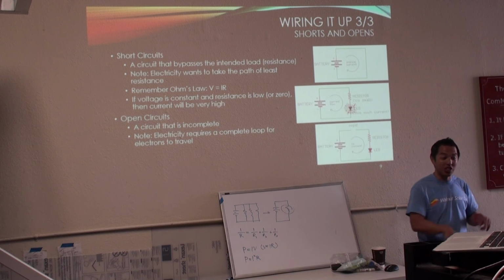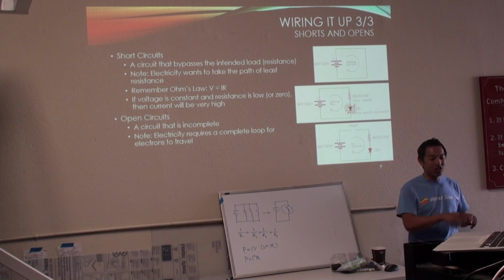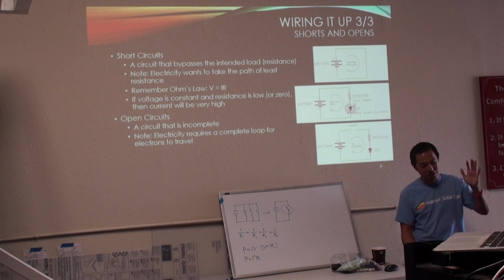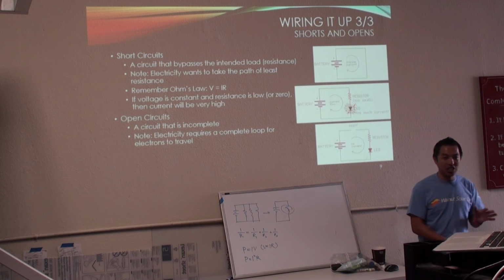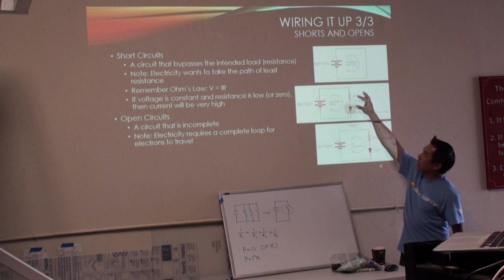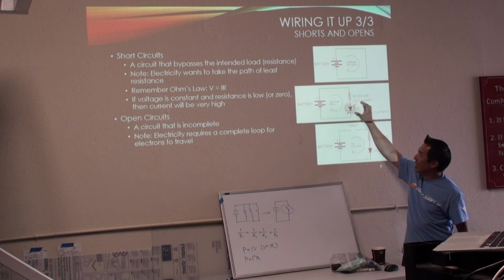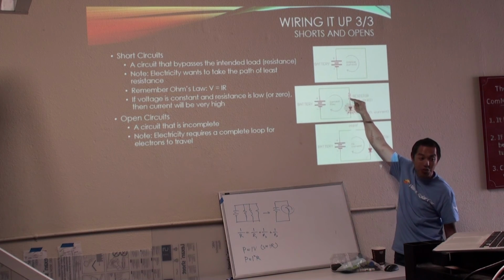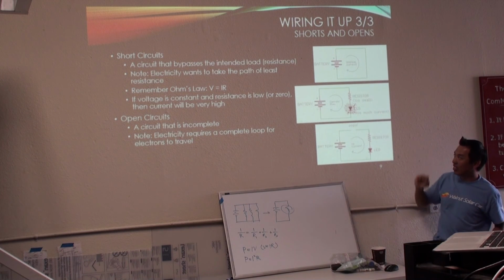Then that short circuit becomes open, and short circuits becoming open is a good thing, right? The short circuit is something you didn't want in the first place, so you blow that to say, I don't want that circuit. Okay? So it will protect your components, because if you had a small resistor here and you had this LED that required a certain amount of current, and you drive it way too much, it's just going to blow that up. Instead, if this was a fuse, for example, this would blow first, then no more current goes there. That's how it protects against a short circuit.